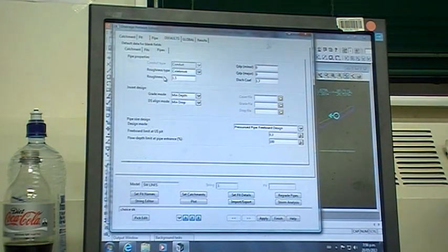This is how we're sizing the pipes, okay? We're taking our rational formulas giving us our flow. It's then going to run a Colebrook-White calculation, and using the grade, the roughness and that flow, it's going to give us the required pipe.